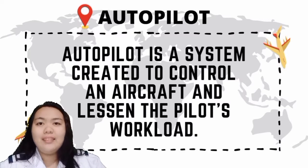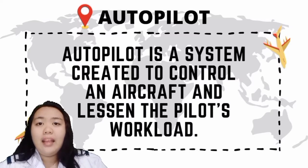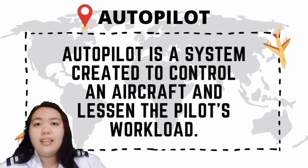What is autopilot? Autopilot is a system created to control an aircraft and lessen the pilot's workload. The autopilot has the ability to maintain altitude, climb or descend to an assigned altitude, turn to and maintain the assigned heading, intercept a course, guide an aircraft between waypoints, and fly or land in a precision and non-precision approach. The precision approach uses ILS or Instrument Landing System, or MLS or Microwave Landing System. In the non-precision approach, it uses VOR, RNAV, and DME.